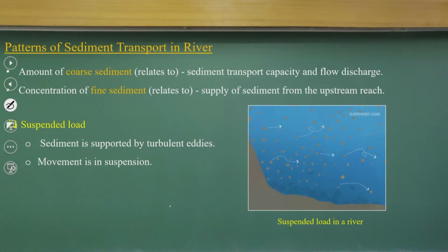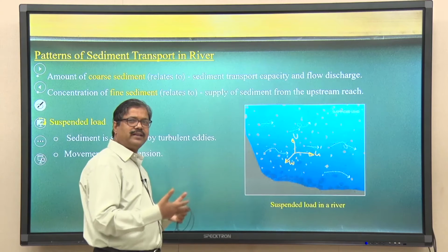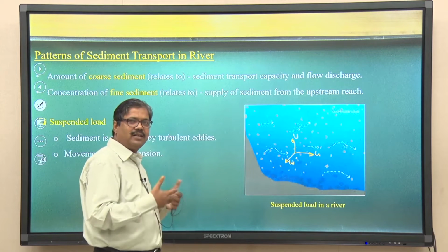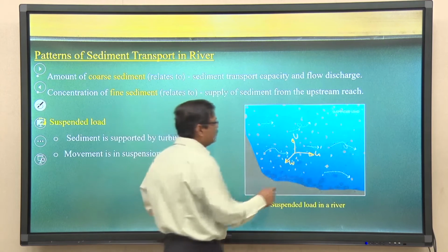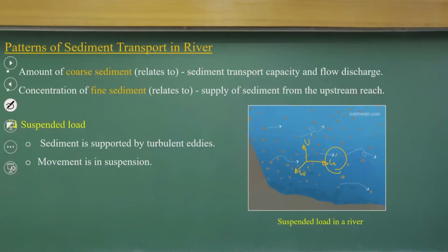Now, if you look microscopically at what actually happens when you have flow, for the suspended load the basic concept is turbulence. It all depends upon the fluctuating velocity components in three dimensions, which are responsible for generating eddies and mass exchange between the layers in different directions. They also generate the shear stresses, or equivalent force component, because of the fluctuating velocity components.